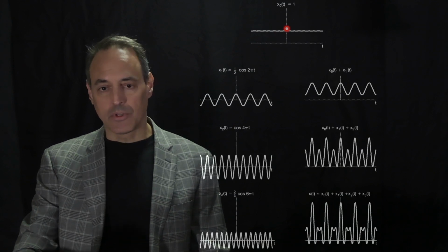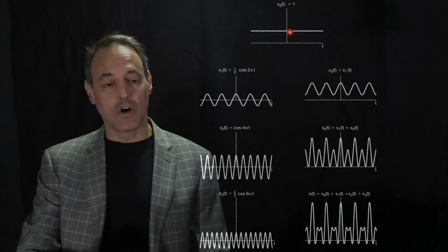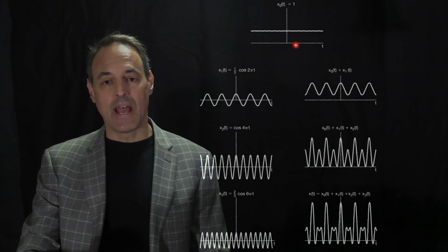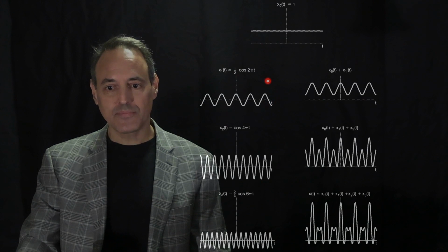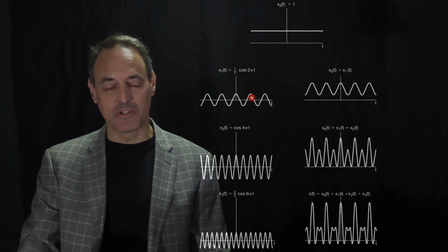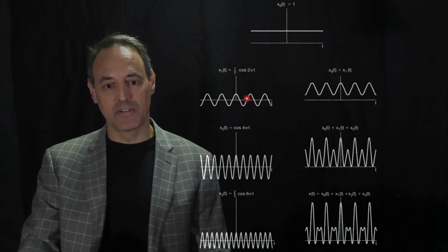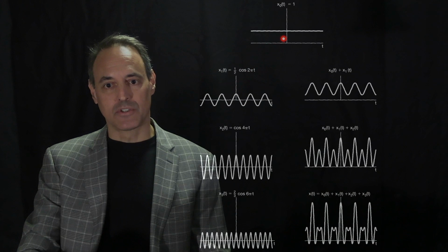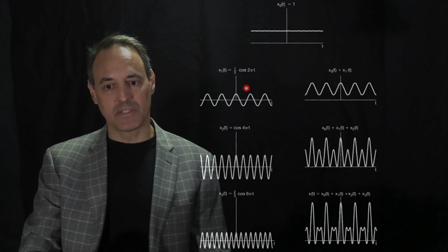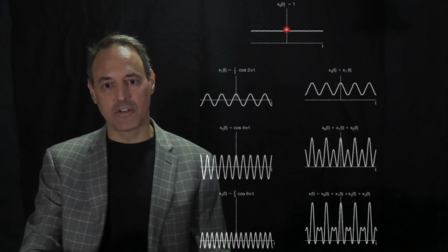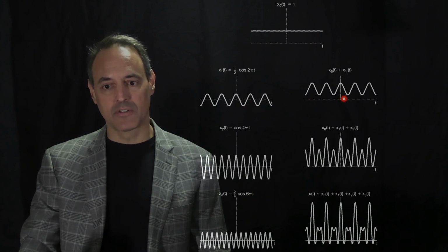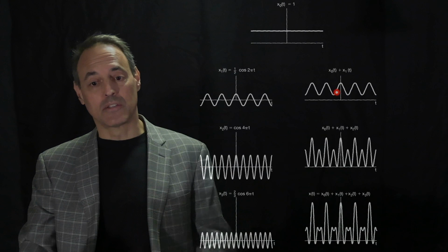Okay, so that sum of signals results in this kind of expression, which then if I start to plot it, here's what the first mode looks like, x naught. So if I just have the sum start from 0, this is it. Now I add plus or minus 1. Here's the x1 component that's there. It's just a cosine with a certain period, 2 pi. And I'm going to add these, so it's going to be x naught plus x1. You notice x naught is just a constant, x1 is an oscillation. You add them together, and now it's an oscillation offset with a constant.